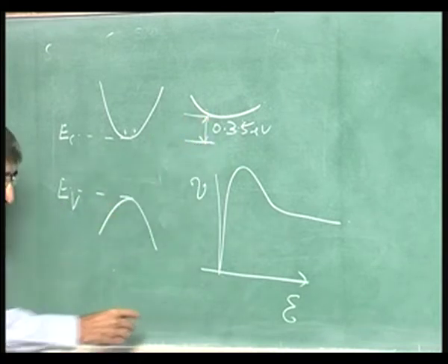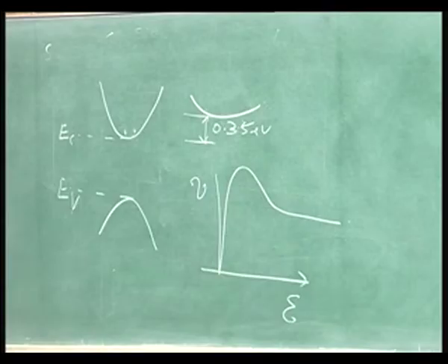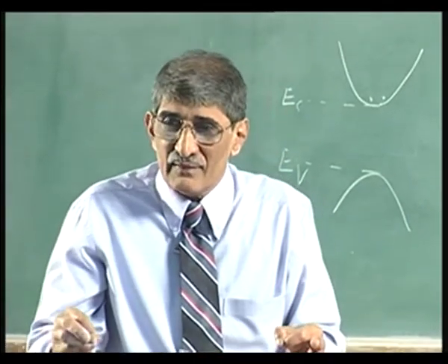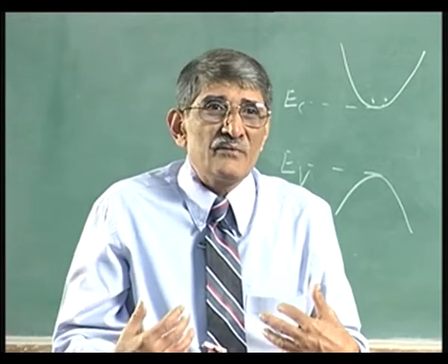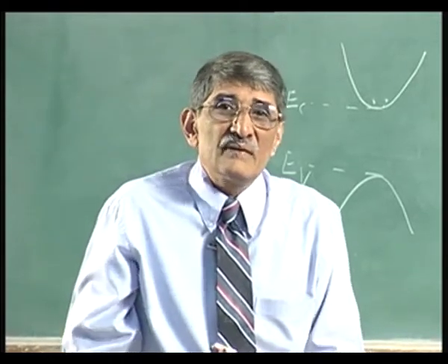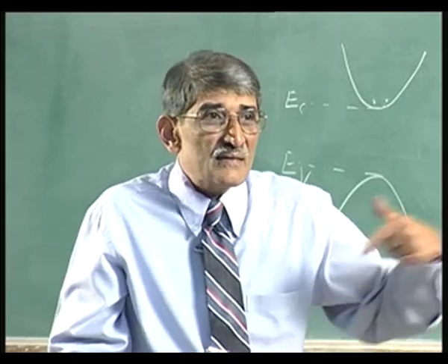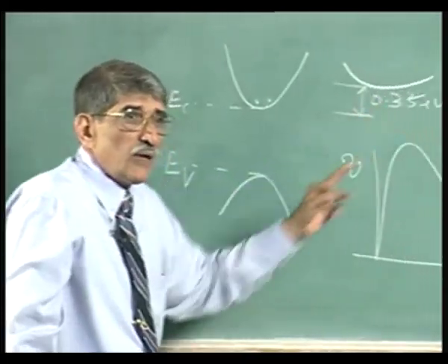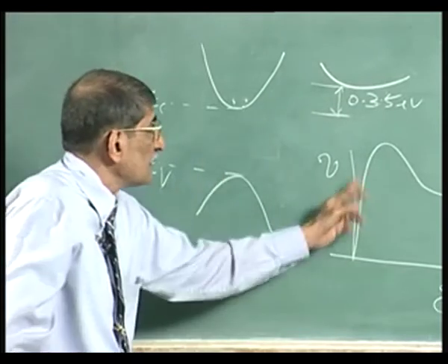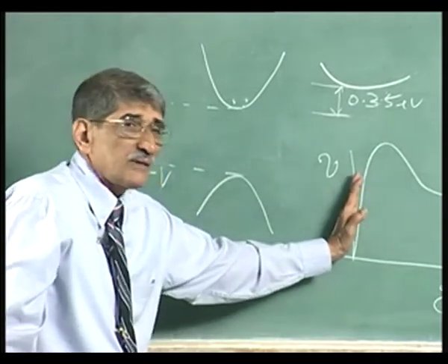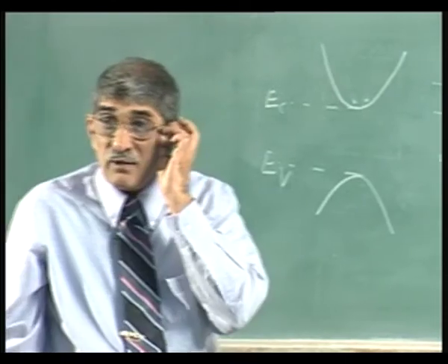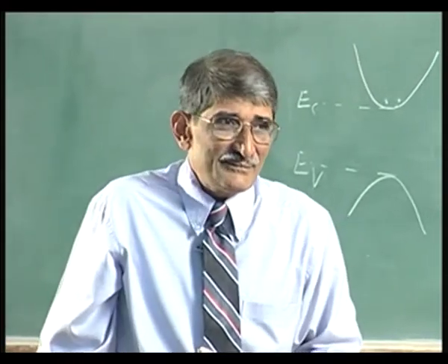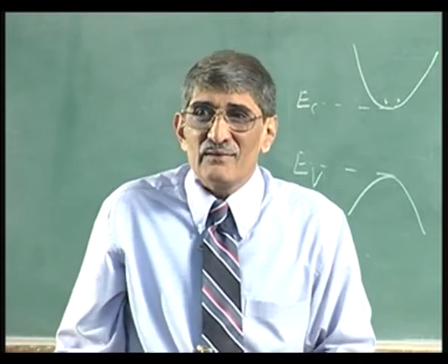So, what happens is the electrons reside in the lower valley, and the entire transport takes place in the lower valley itself. Virtually, people talk of the transport of electrons without inter-valley scattering. So, one scattering phenomenon is cut down. So, it is a very high mobility right through all the way. V will be mu into E, that is all. That will be the type of velocity.